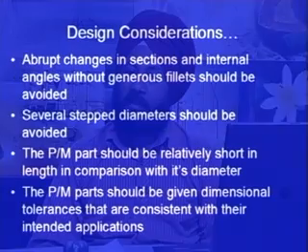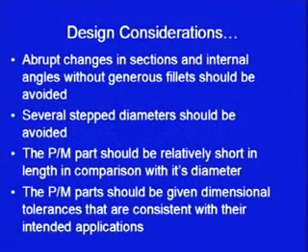Similarly, internal angles without generous fillets should be avoided. So, we should be very generous in giving the fillets. We should use a fillet radius. If a fillet radius is not there, and we are making sharp edges or sharp corners, then there are chances that abrasion may take place on those edges and we may not get the desired quality of the powder metallurgy product.